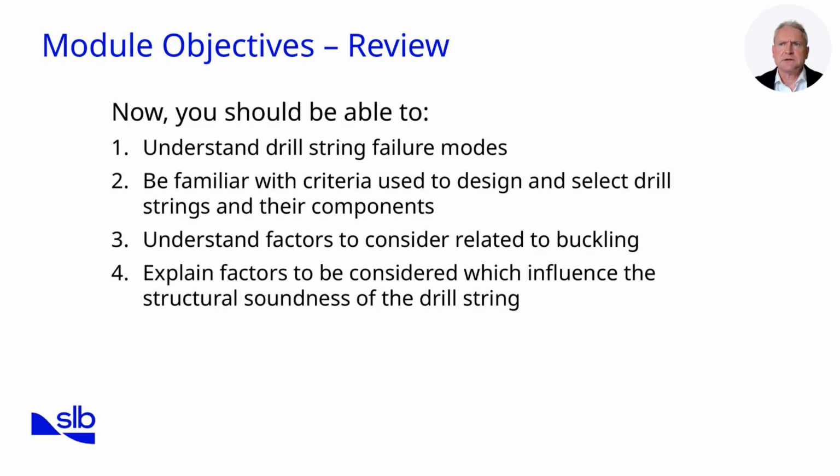A major focus was on buckling. We differentiated between sinusoidal and helical buckling, discussed the Dawson-Pasley model for calculating critical buckling loads, and examined how inclination and wellbore geometry influence pipe stability. Practical tips, such as maintaining the neutral point in drill collars and using engineering software to model each BHA, were emphasized.